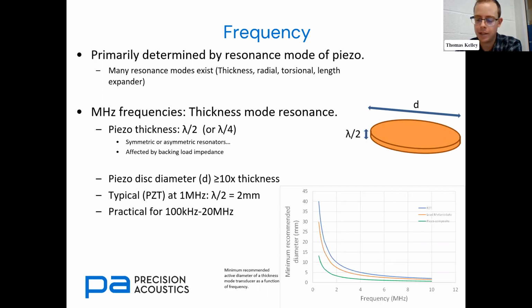As we said, the PVDF is not a resonant structure in the same way as other ceramic materials. Whilst the frequency is affected by the thickness and there is a bit of a resonance, it's very much less well defined than for a lot of the more resonant materials, if that helps. Yeah, I think so. It's clear how you have the influence on capacitance through the diameter, but as you're saying, this PVDF film behaves in a special way, and the capacitance really affects the whole mode of operation, basically.